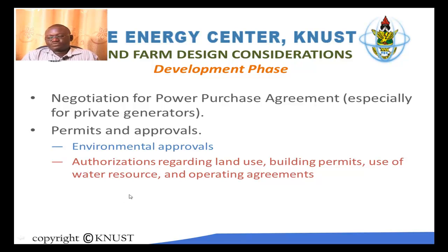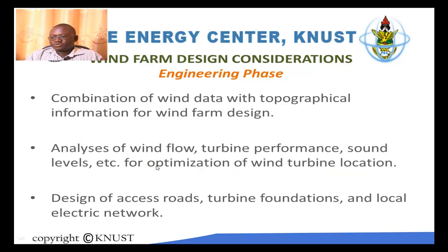Then you move on to the very important phase, the engineering phase, where most of the things to be done are actually designed. And so here, some rigorous or detailed analysis of the wind speed data is done in combination with the topographical information of the site, so you can know exactly at which points will be the best places to actually place the wind turbines.